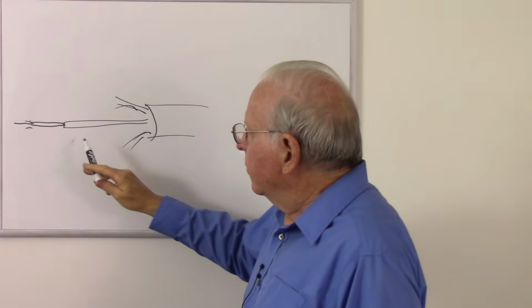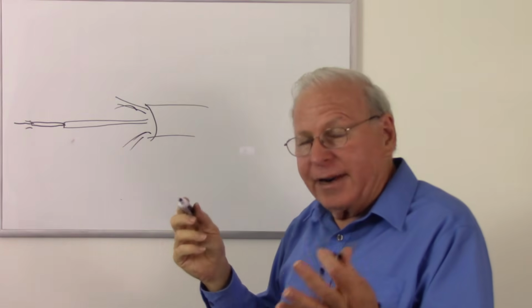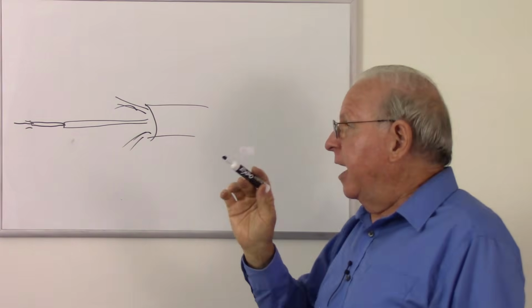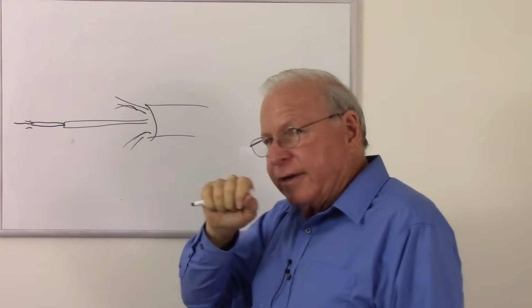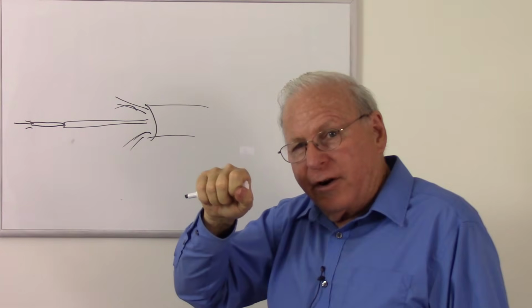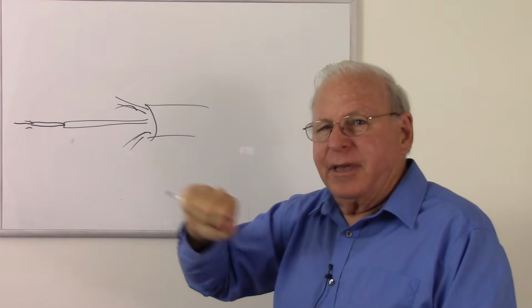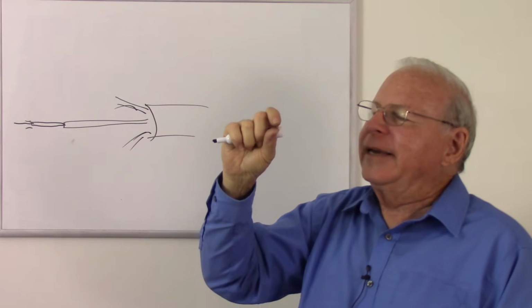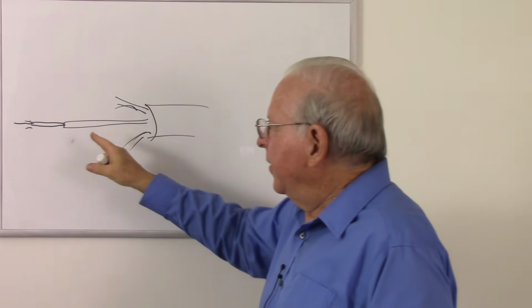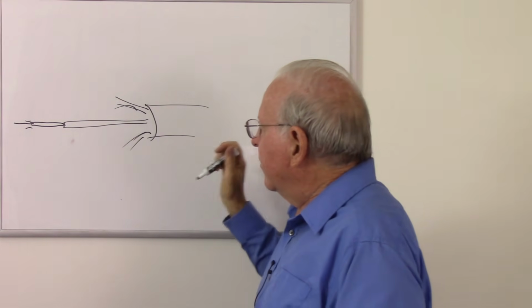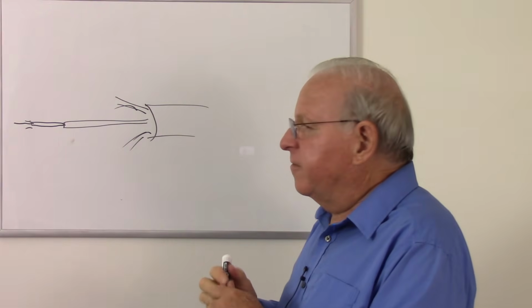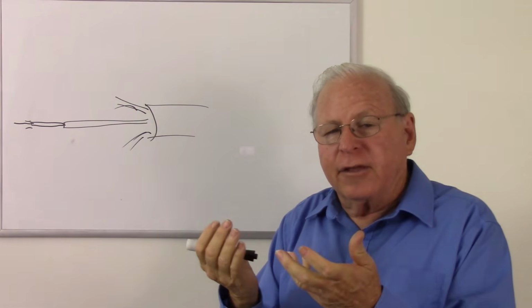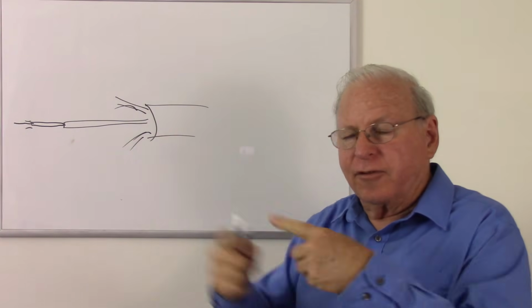And typically when we're working with this, if you happen to ever hand terminate it, you're going to want to strip off all the buffer, leaving just the glass fiber. So when you strip it, make sure you get both the secondary buffer, which is the big heavy PVC, well, heavy as far as 900 microns is concerned, which is about a millimeter, and then make sure you're down all the way to the glass. So that's going to be what's called your tight buffered fiber, and it comes with one fiber coming through, or sometimes they're bonded together to make zip cord or duplex cables, so you have transmit and receive.